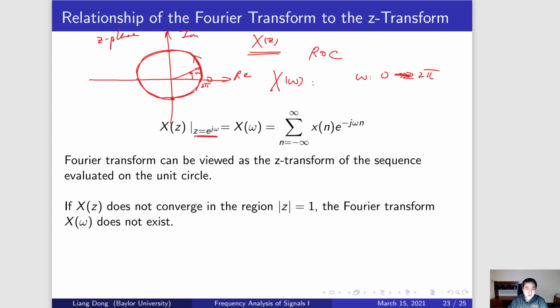Now we see exactly from this picture, because it's a special case of the Z-transform, we travel along the unit circle. Of course, when we circle back and cross over 2 pi, that will give an ambiguity of 2 pi times k. That's exactly what we have here, the period of 2 pi. If you go beyond that, it will repeat itself in X(omega). So remember this correspondence.